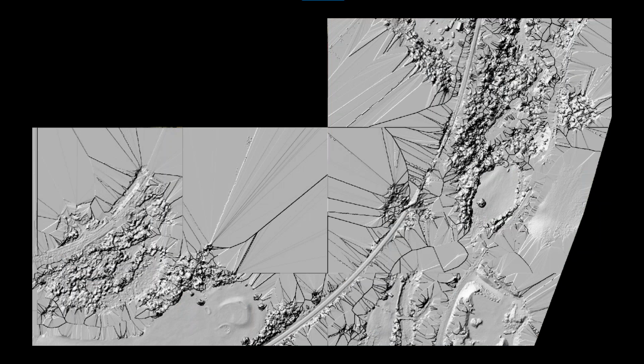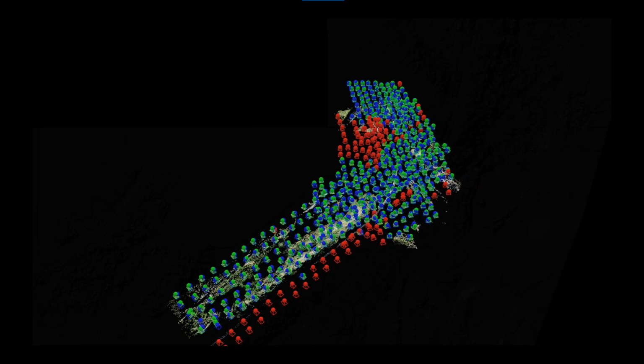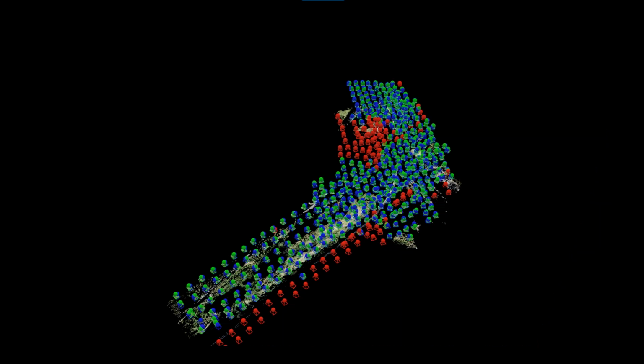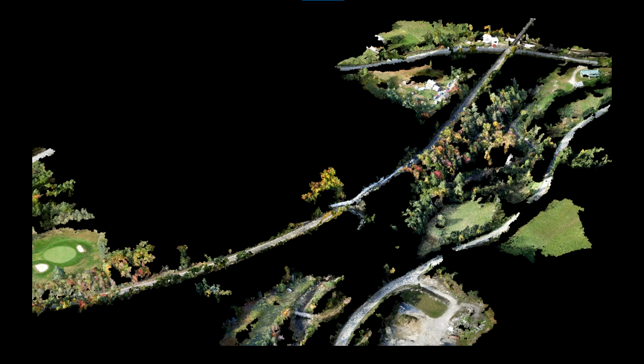If we move into our photogrammetric software, okay, so these are things that you might want to specify in a report. We use Pix4D. Jon over at Airshark uses Agisoft, very similar workflows. We can get this output here and show you the area that we acquired and where the images failed to ortho-rectify. And then we can go ahead and take a look at that point cloud. We've got excellent surface models and points, elevation points for the train tracks and some of the open field, really breaking down in these steep slopes and these forested areas there. So not working well at all. So let's sum it up there.